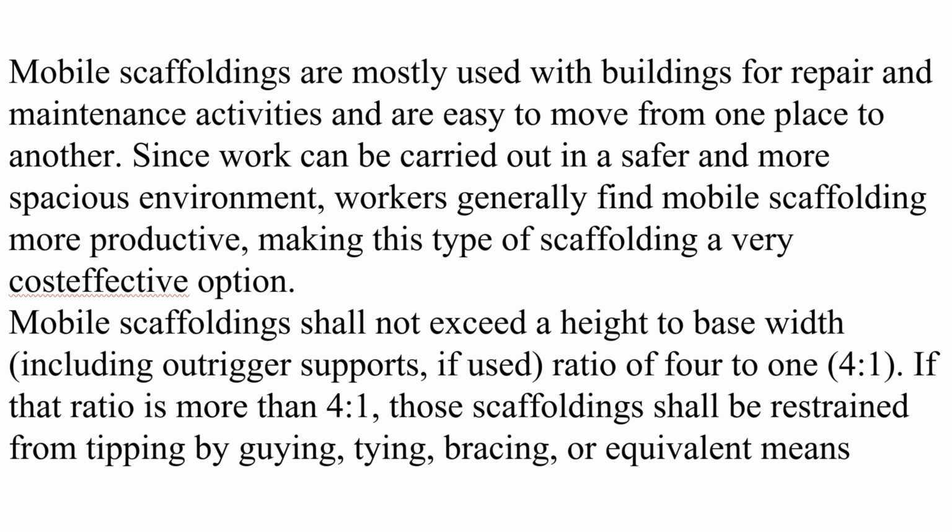Mobile scaffoldings shall not exceed a height to base width ratio, including outrigger supports if used, of 4:1. If that ratio is more than 4:1, those scaffoldings shall be restrained from tipping by guying, tying, bracing, or equivalent means.